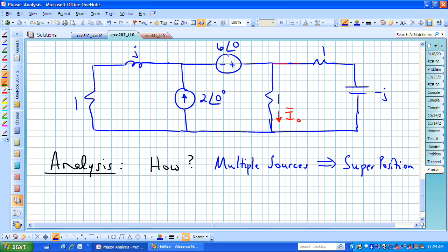Suppose that somebody said, well, I see some meshes there, so I'm thinking KVL. If you look a little more closely, initially you see these 3 meshes, and then you say, wait a minute, if I had a mesh here, a mesh here, and a mesh here, I don't know what's going on with this voltage drop up or down because of that current source.